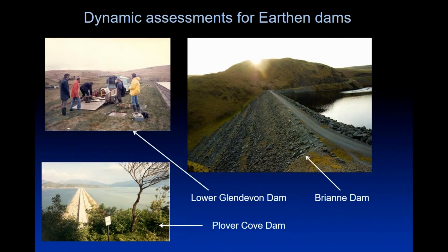And if you look carefully, you can see that the coping stones along the crest have been forced by the valley sides moving in towards the center. They've raised in the middle there. So we looked at the behavior of that dam and found that there was a weakness in the middle. But that would not be important if we lowered the reservoir level, and in fact not by an enormous amount. And that continued to be the case. There's a swarm of very minor earthquakes underneath that reservoir.